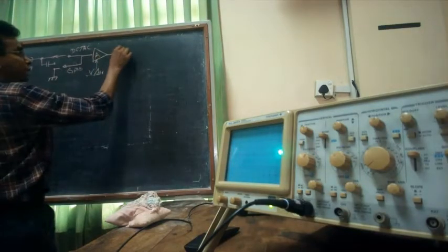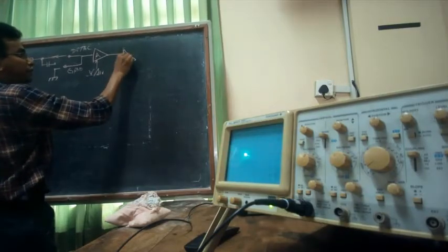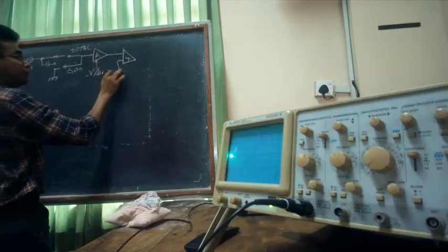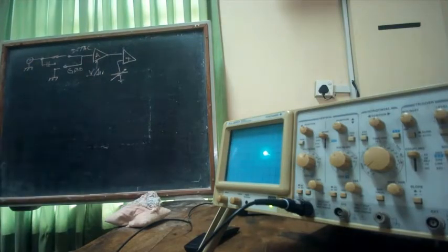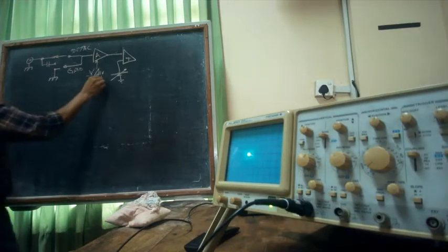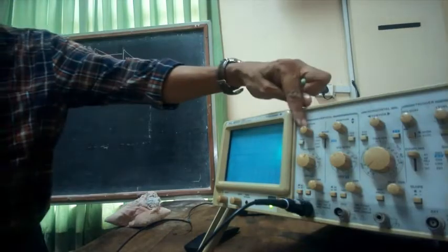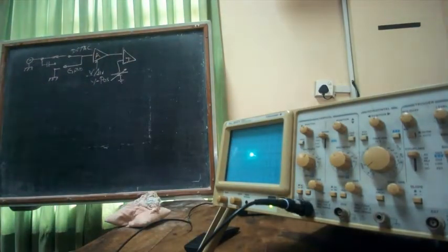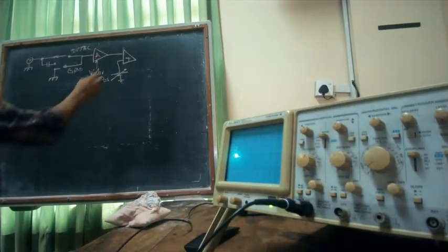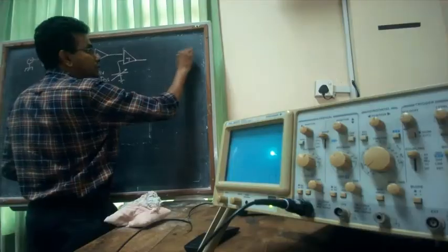And then you also have an adder which adds this position control. It's the Y position control, so channel 1 Y position control. This is this one right here, right? And that goes and connects to the Y plates.